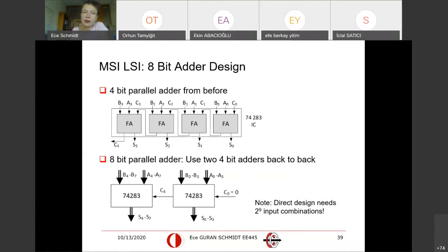How do you get a 4-bit full adder? So in that case, if you look at this circuit, this is a single block. It is getting a carry in, 4-bit operands, addends, and it is generating a 4-bit sum and the carry out.